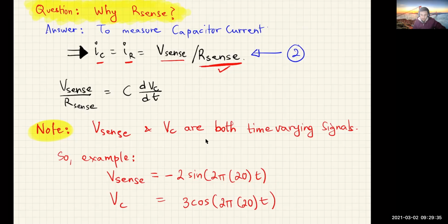What I'm saying, if it's not very clear, is let's say this is what you saw on the oscilloscope. The oscilloscope will have some arbitrary time equals 0 position depending on your trigger, but you don't have to pick that as your t equals 0 point. If I pick my time equals 0 right here, then this signal looks like a sine wave now, right?